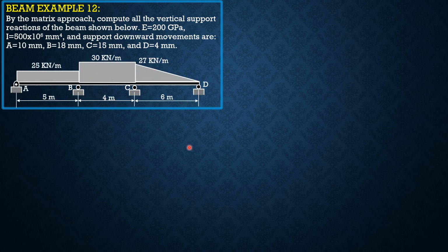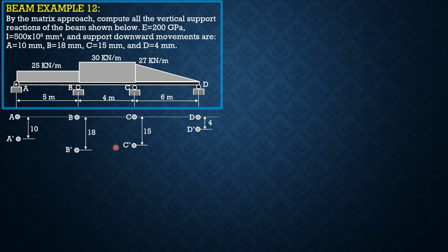So here is the given beam. So let's have our guide. Then we compute fixed moments, which consist of fixed moments due to the load and side sway moments. So let's just assume the direction of the fixed moment shown. If it does not conform to the assigned direction, then let's just make the direction negative.